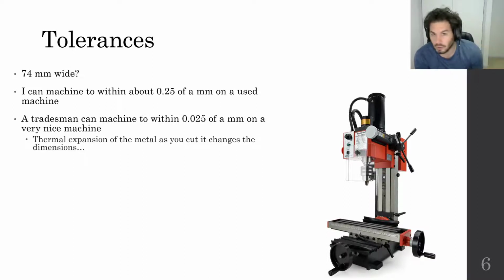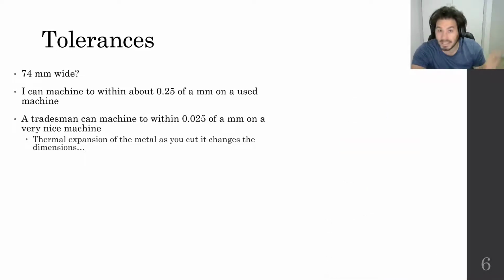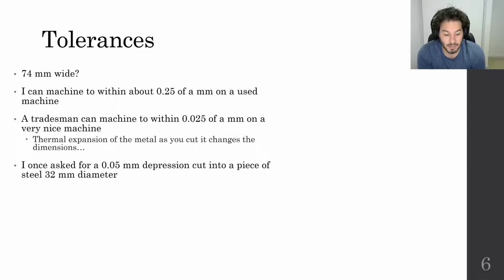This just keeps going, and you get to the point where you're looking at highly precise machining, and people are actually having to calculate that when you machine, you heat the object up, and it thermally expands as a result. Then you cut through the thermally expanded material, and it shrinks when it cools back down, and you end up with cuts that are slightly bigger than you expected. So you're having to compensate for that type of thermal expansion to get that tighter tolerance. And it's turtles all the way down. It just keeps on going. Sometimes it matters, and most of the time it doesn't.